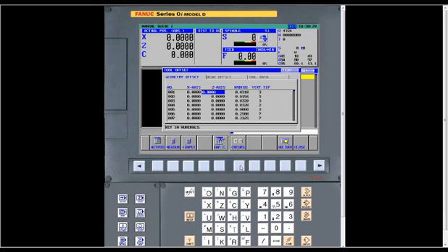Now we'll change the cursor as we page over. The next value that we need to fill out is the radius. And what that's asking for on a turning tool is the radius of the actual insert. So that's what it's asking for there. I know on my tool, this is an 80-degree left turning insert. I'm using a 31 thousandths nose radius tool. And where I get that number from, let's do this.